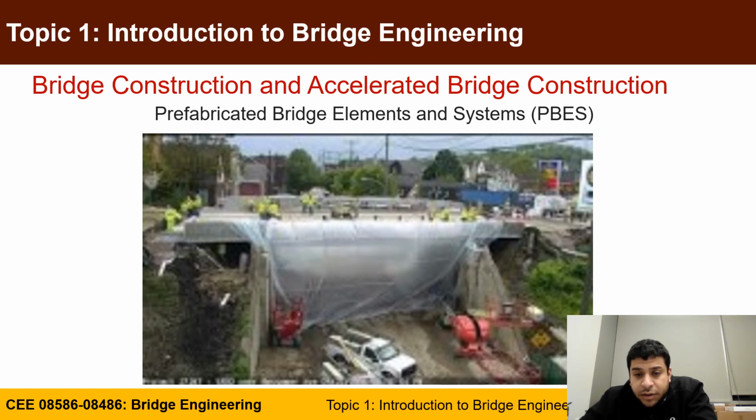This is the final side module, and you will have a lot of backfill behind the abutments. As you can see, work is in progress for the second night to seal the bridge, having the bridge in a few days rather than with cast-in-place technologies. You now have accelerated bridge construction.